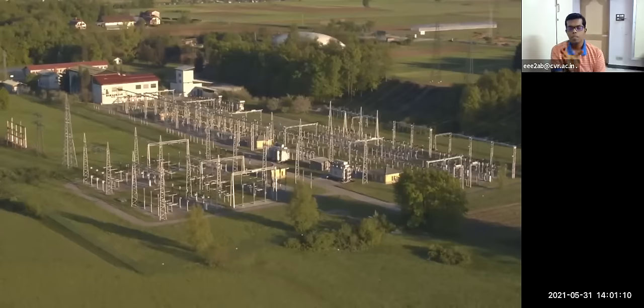That's why the definition of substation goes like this: it is an assembly of apparatus in which you can change the voltage or change the frequency, power factor, everything. The assembly of apparatus includes power transformer, circuit breaker, potential transformer, disconnectors, surge arrestor, insulators, and many things combined together to form a substation, and also capacitor banks for maintaining the power factor, reactive power. Everything is combined together into a building or a closed structure, sometimes an open structure. That also we'll see, why it is open.